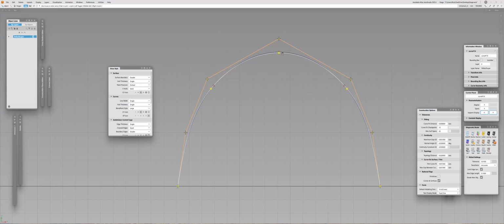Apart from that, there can be some issues with texturing, but there are not a lot of people who do texturing work, so in this regard, it's not important. Now, in 99.999%, everybody uses uniform. There are a few exceptions in the automotive industry where sometimes you really need chordal, but it's extremely rare. In my practice, I never encountered it myself. I know that some other people do. I didn't. And in general, for professional or casual, it doesn't matter where you work. Even if you're working for automotive, chances you will be working with chordal are very slim. They may be, but rarely.